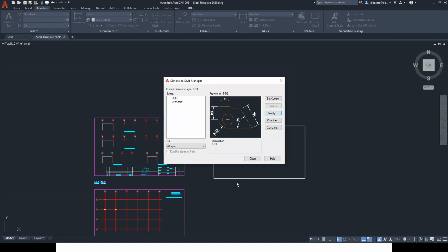And that's, guys, like I said, I've been teaching AutoCAD like this since the very beginning. I know that you can simply do everything in model space and then drag everything into paper space and get the templates and then hope for the best. And I've been hearing a lot of complaints from students saying we always have a problem fitting our drawing onto the paper. Am I correct? Yes, sir. You see? So by dictating at the very beginning what your limits are based on that printable area, you'll never have that problem.